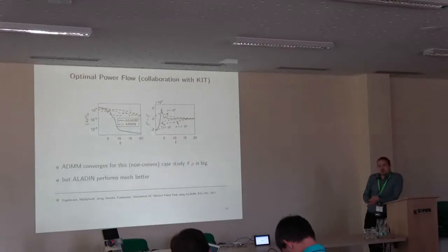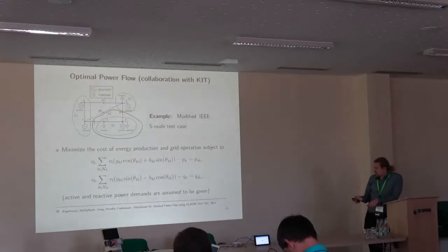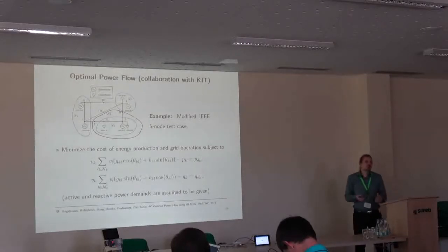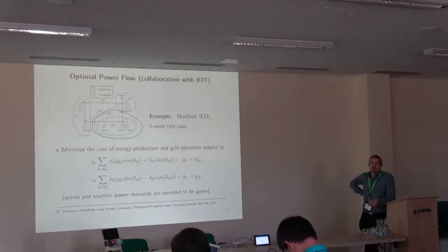And if you change rho, could it be even better? No, actually, it's not, since in this case we can compute the Hessian matrices. Here, these power flow equations look horrible. They are non-convex, but we can compute second-order derivatives of this, that's not a problem. So we can scale with exact Hessians. That hasn't been an issue here. This case is nicely smooth, so the auto scaling works.